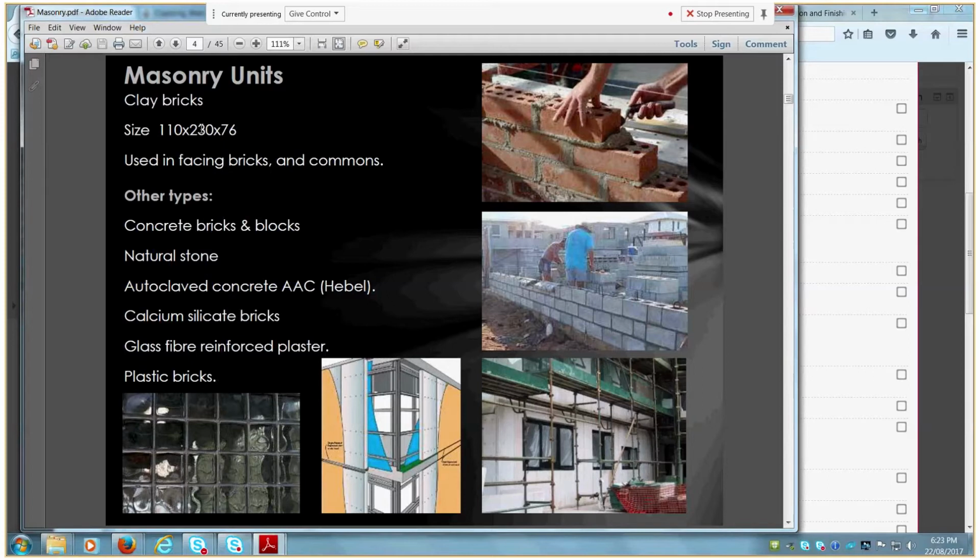The dimensions of your brickwork will determine where you place your windows, and also the size of the windows that are used and produced. Your various window and door manufacturers produce their windows as per brickwork dimensions, but the placement of your windows on the wall, as a designer, you should do in accordance with the brickwork dimensions.